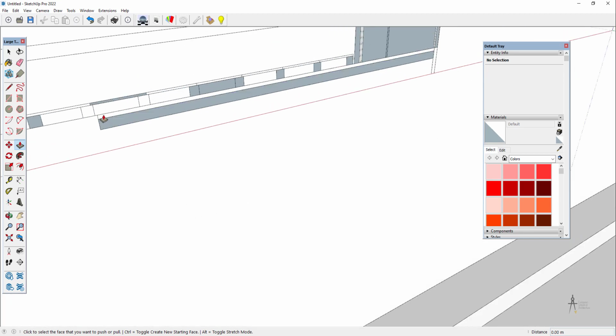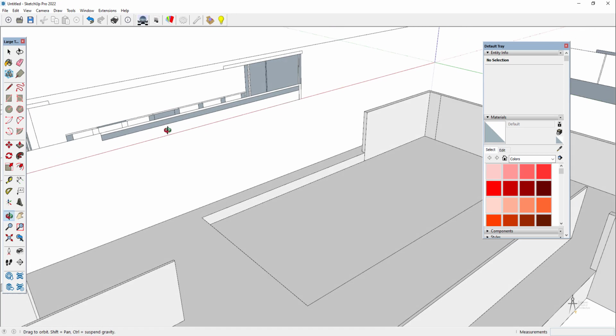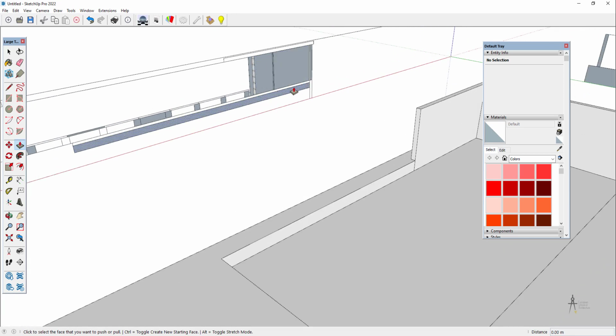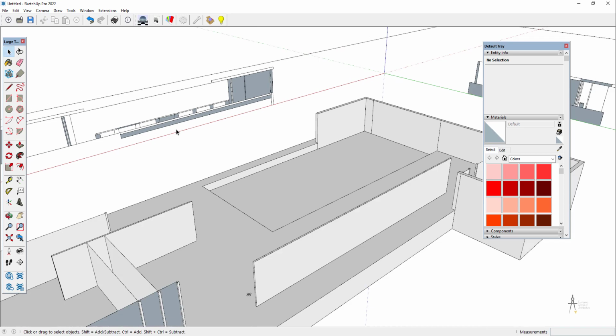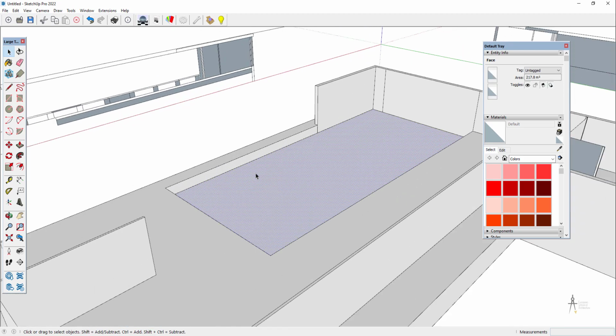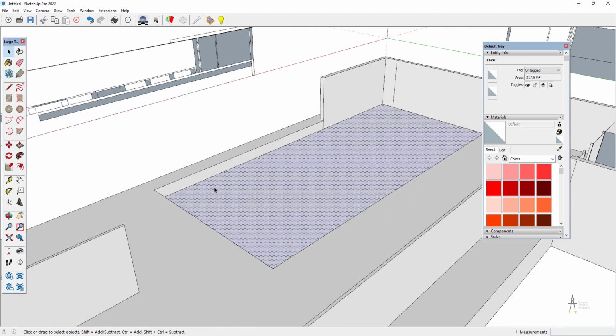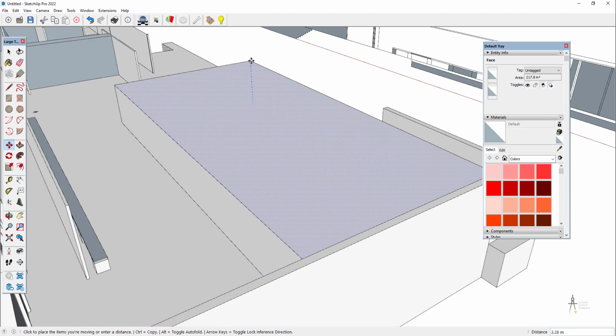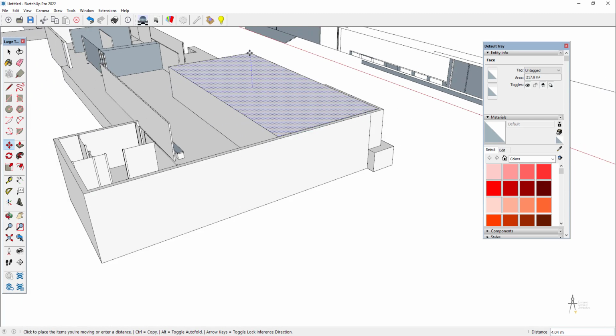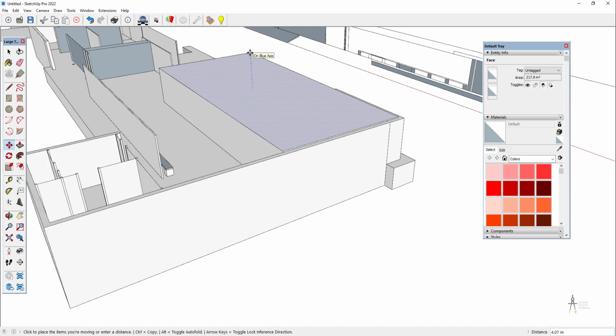And what's the next stage? If you can see that line there, that line is where the surface of the water is. So I need to do a rectangle that is at that altitude, to express the level of the water. I'm going to copy this rectangle using the Move tool and Control, in the blue axis, because I want it to be vertical.